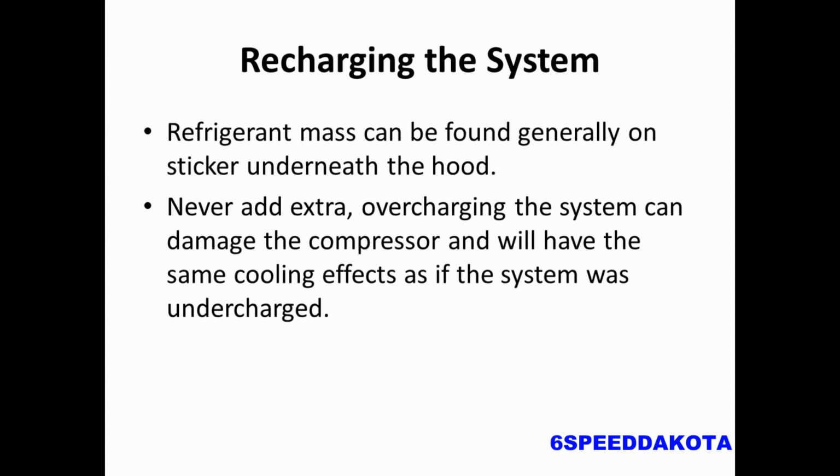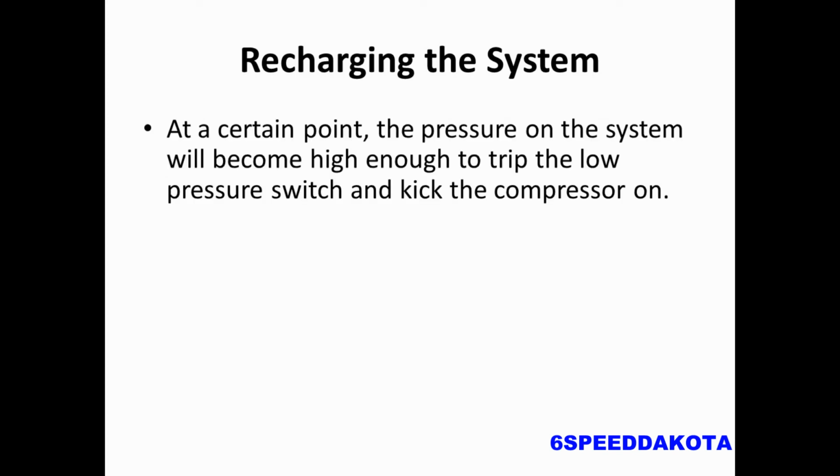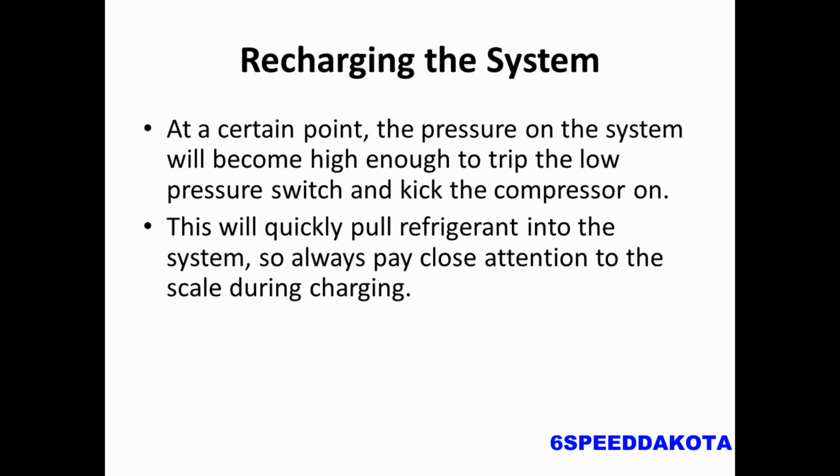Don't ever add any extra refrigerant because overcharging the system will damage the compressor, and it has the same effects as undercharging the system. You won't get as cold of air. So when starting the recharging, the refrigerant will slowly enter the system just by the pressure in the tank pushing the refrigerant into the system because the low side pressure switch hasn't been tripped yet to start the compressor up. At a certain point, when the pressure in the system becomes high enough to trip the low side pressure switch, it kicks the compressor on. What this will do is quickly pull the refrigerant from the system. So you always have to pay close attention to the scale during charging.